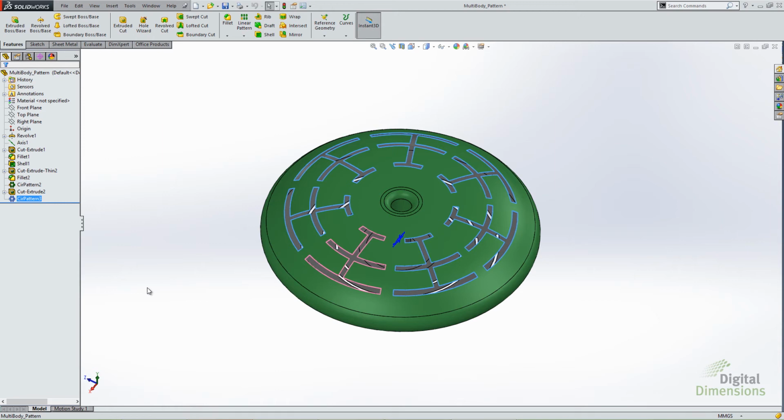So now whenever you select a pattern in your feature tree, it'll highlight the seed feature. And this is for those of you that had to hunt down the seed feature. Sometimes people would even make them separate colors or have different ways of distinguishing the seed feature from others so they could find it easier. Well, now when you select the pattern from the tree, it's going to highlight in a different color.